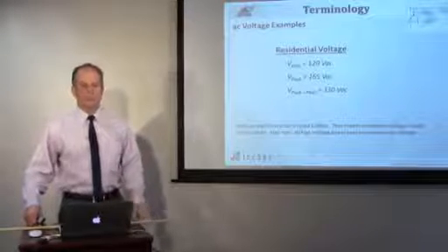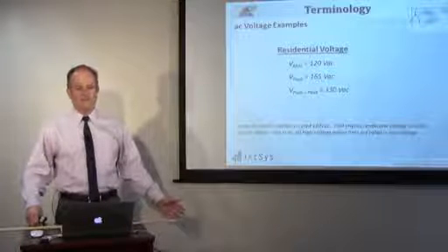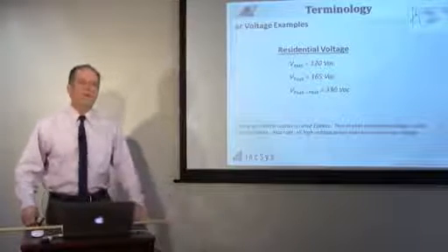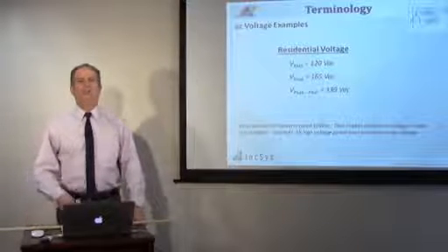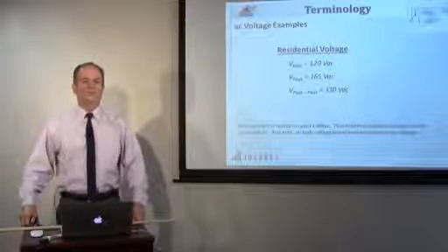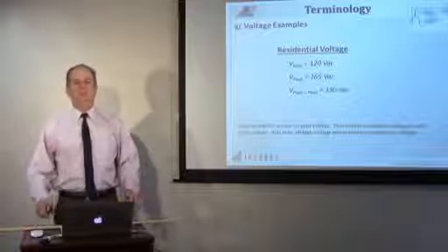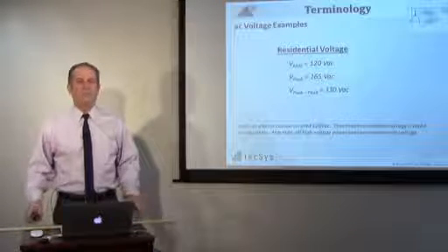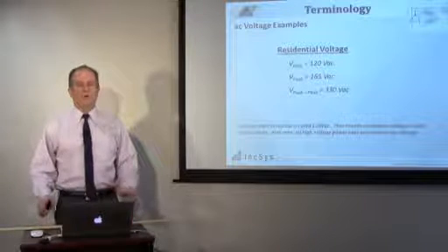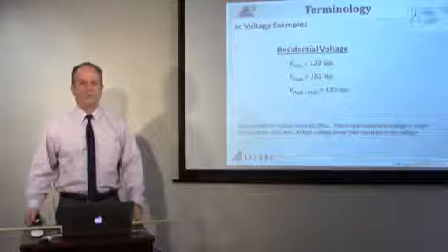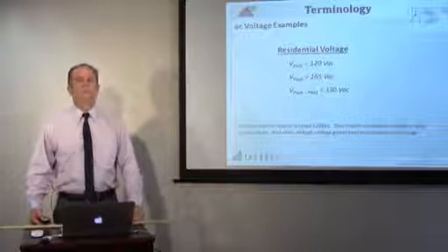Well, in power systems, our transmission lines are rated RMS like we talked about, and our household residential is RMS, but we might be talking about peak voltages when it comes to ground potential rise or lightning, or when it comes to faults on the system. We might be talking about peak events. There might be some insulation levels, so we're talking about our BIL levels. So voltages have different terms for different reasons, and this basically explains those different terms.